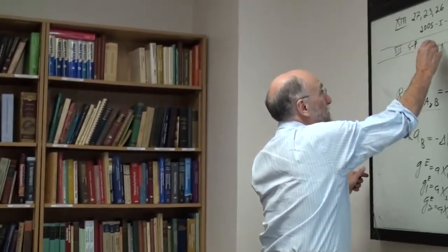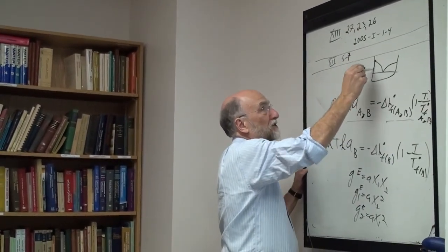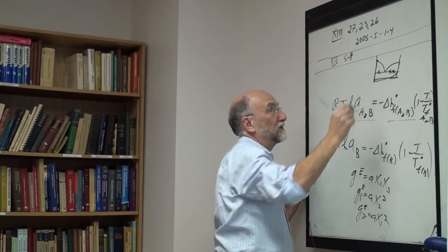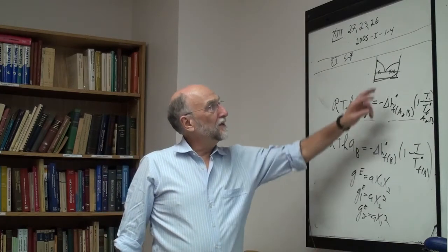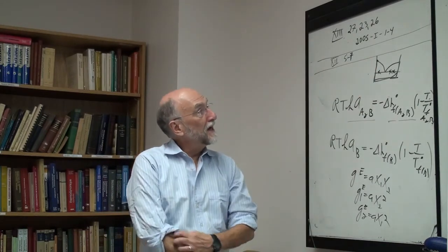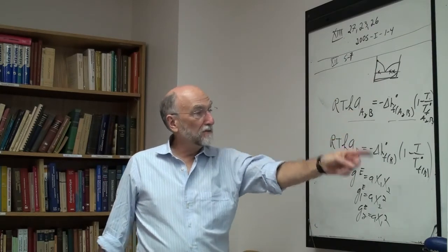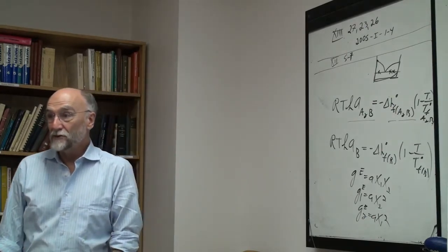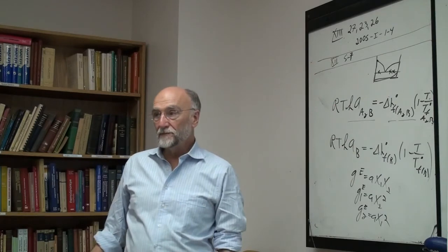So if you have a phase diagram and you don't know much about it, but you're pretty certain it's a eutectic mixture with very little solid solubility, and all you've measured is the eutectic temperature, which is easy to do on a cooling curve, and it's not too far from ideality, you can probably calculate the eutectic composition and the regular solution parameter with reasonable accuracy as a rough estimation, just from the one datum of the eutectic temperature.